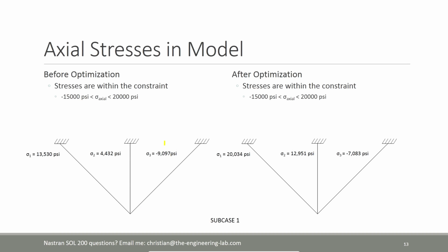again, the optimizer will vary the parameters, your design variables. It will continue to do this until the objective has converged, or if you've hit one of your constraints. Here, the optimizer has gone from 13,000 psi, and it went all the way until one of the members touched the ceiling in the design constraint bound.